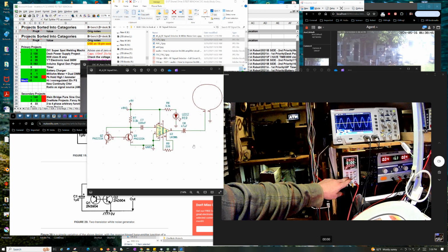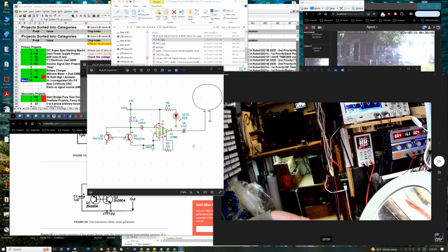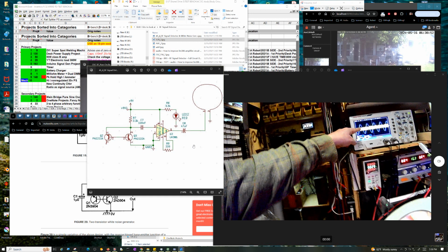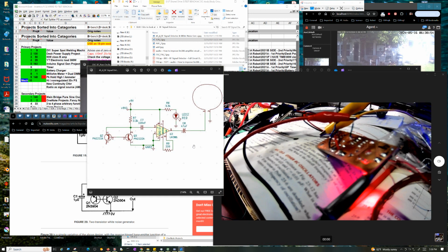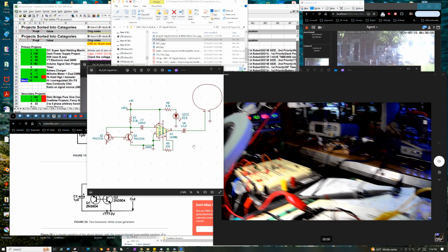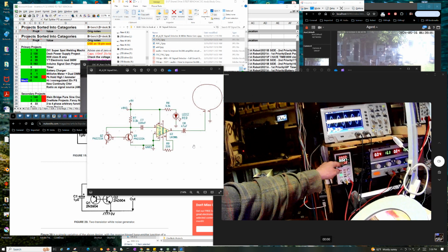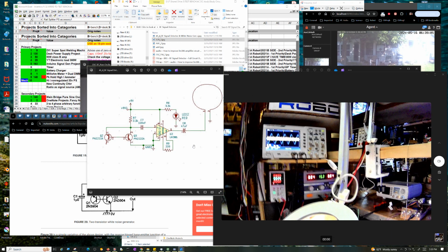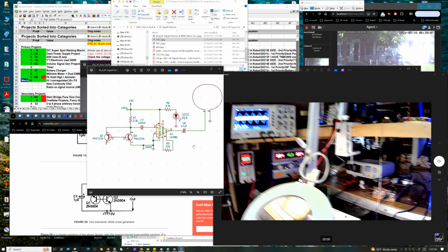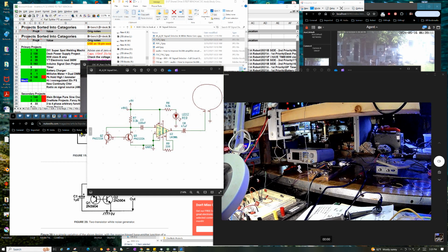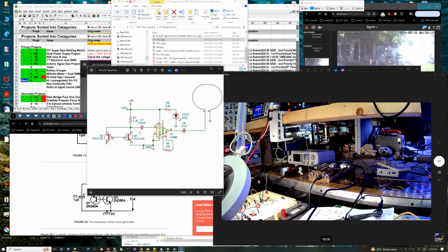But if you turn this thing on, it starts out about 32 milliamps, and you can see the noise coming out across the coil, which I got my oscilloscope probe right there on the output. But this current does fall as this thing warms up, so eventually it becomes less and less noisy, and it becomes kind of spotty.